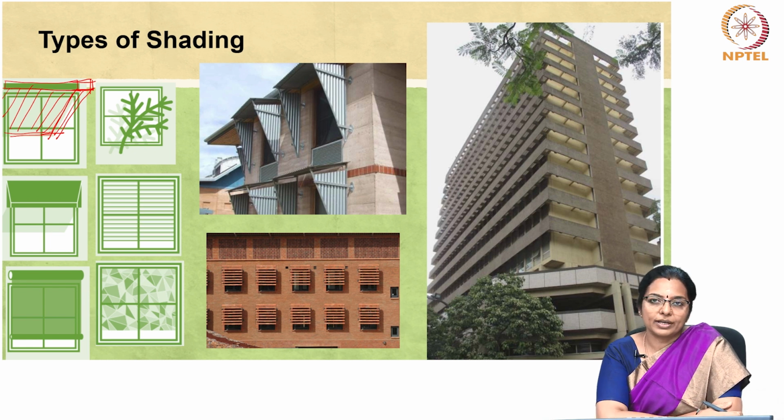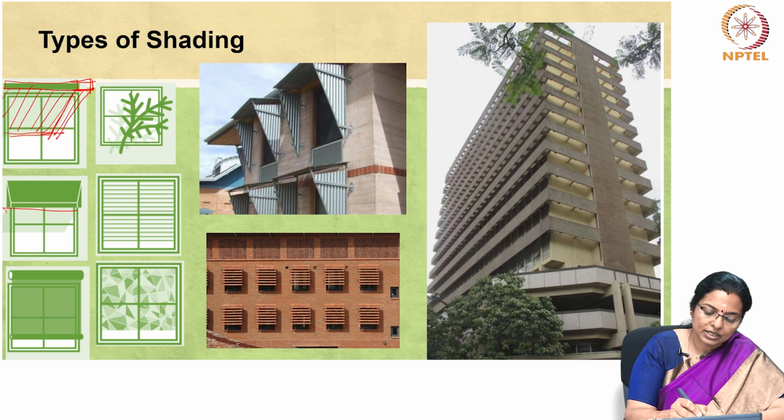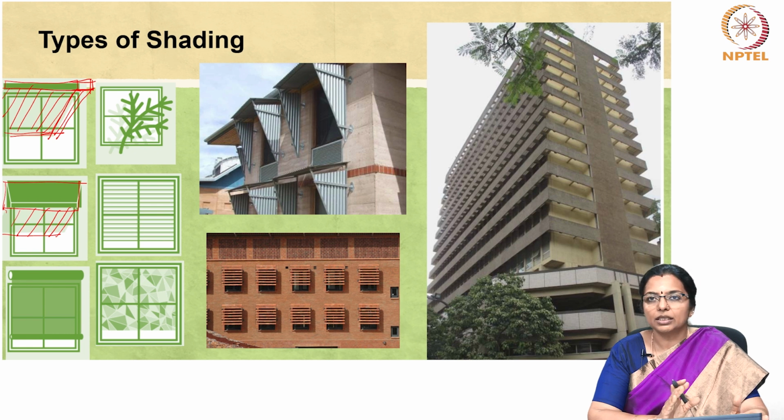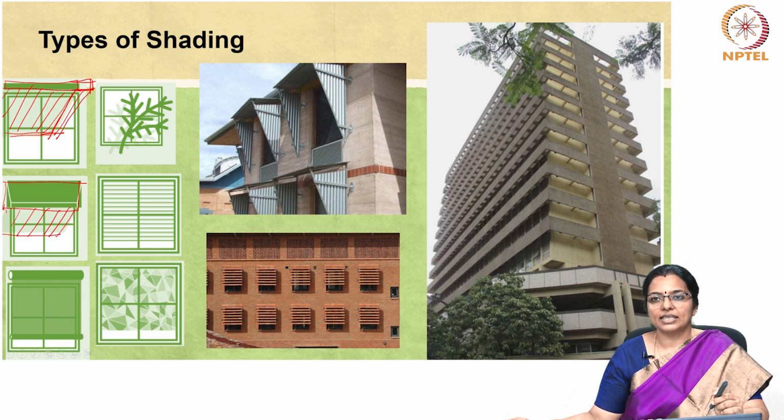Then second is awnings. Awnings, like overhangs, block sun effectively. Awnings often extend further than overhangs, and normally they are considered best on east and west facing walls. So, these are awnings. However, on all the walls, what works best, at least in the tropical country, is overhangs at least. Then you can have exterior roller screens or shades and shutters.